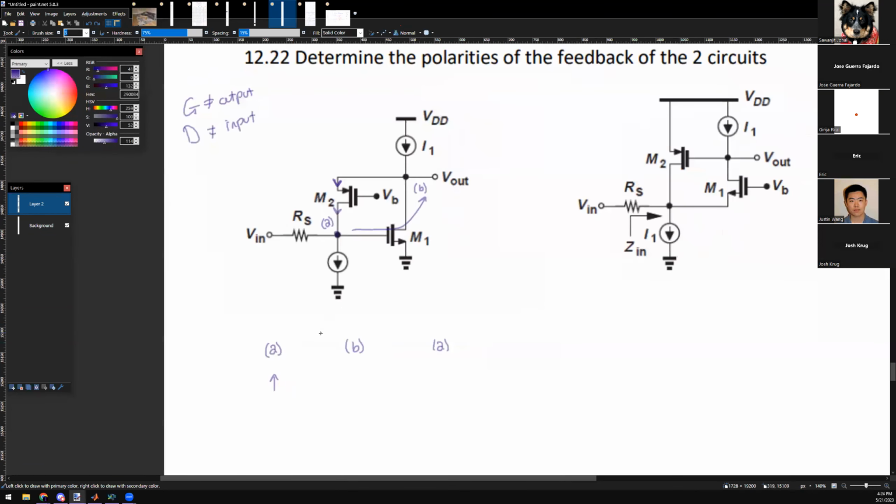Sorry, one more time. What type of amplifier stage is this? Source to drain. Wait, it's like source to drain? Gate. Did you mean to say gate, Justin? Because the signal comes from gate to drain. So which terminal is not being used? The source. So we call it common source because the source is not being used.